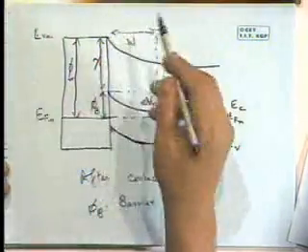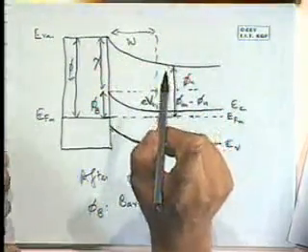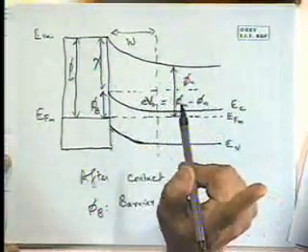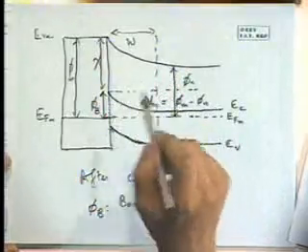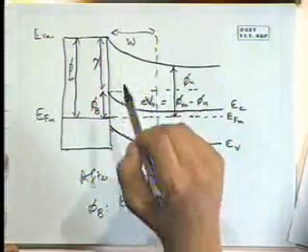because that hasn't changed. When I was discussing chi earlier, I told you that the Fermi level may change with doping, so therefore work function can change with doping, but chi doesn't change. Chi is from the bottom of the conduction band edge to vacuum level, and that has remained constant.